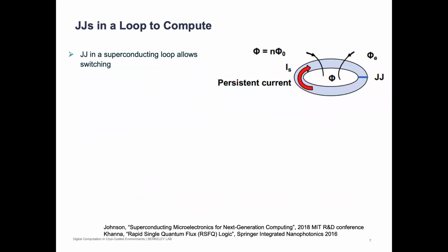So how do we implement these gates? Very simple. Another basic structure in this technology is what's called a SQUID, a superconducting quantum interference device loop. I'm not great with the expansion, but SQUID is always what we call it, which basically is a loop where current goes round and round. You can have one JJ like I'm showing here, but you can have multiple. And the JJs are there to switch and do actual useful compute, but also to maintain state.